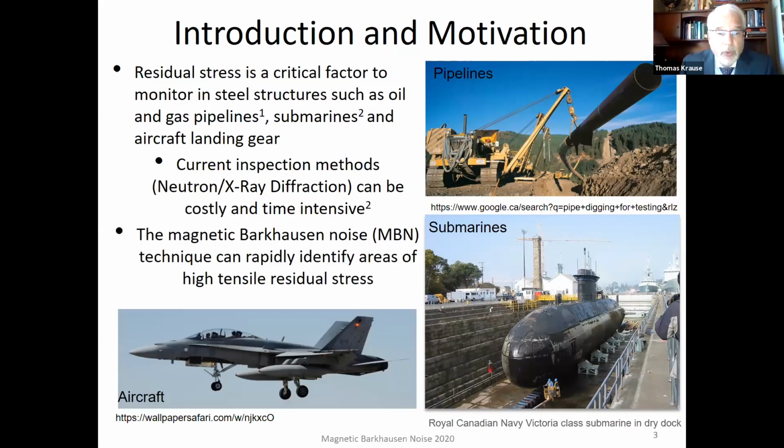So the proposal was originally to look at magnetic Barkhausen noise because it was seen that it was sensitive to stress and could identify areas of high tensile residual stress. And in fact, it is used to inspect aircraft landing gear.